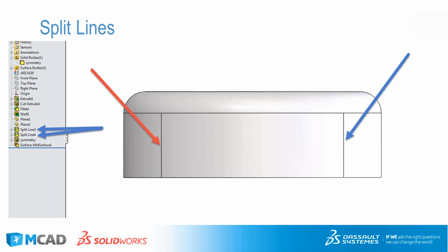On that note, you can also use these split lines for, say, let's say you had an assembly that was bolted together and due to the limitations of the geometry, the virtual connectors won't work. You could actually use the split lines to define where the heads of the bolts would contact and cause pressure on both sides of the plates and effectively at least try to model those kind of pressures accurately on both the top and bottom surfaces.